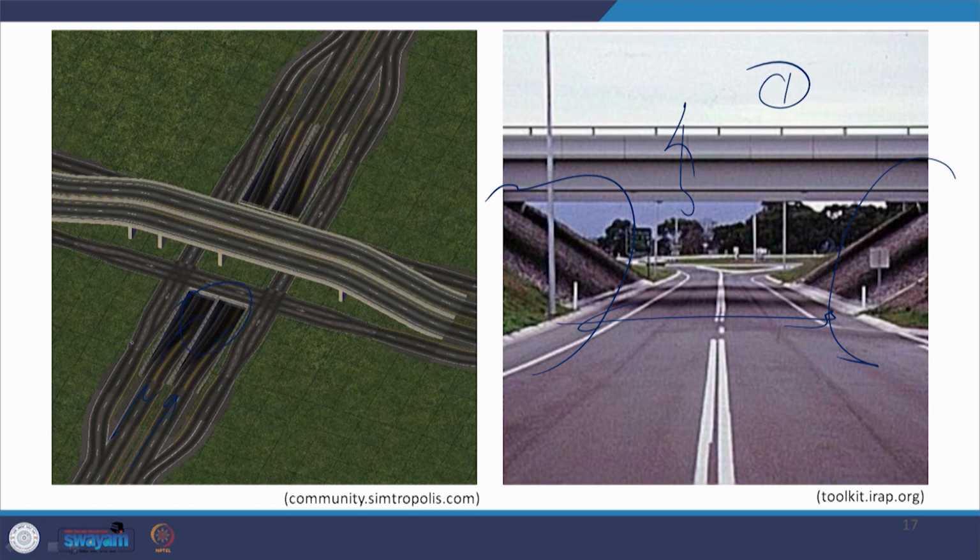So, that is an underpass here, this is an overbridge being provided. For some types of movements, the movements are happening at the ground level. For some crossing movements, those have been done at different levels. So, it is a combination, some things happening at grade, some things happening grade separated, and that is why the total maneuvers are being taken care of.